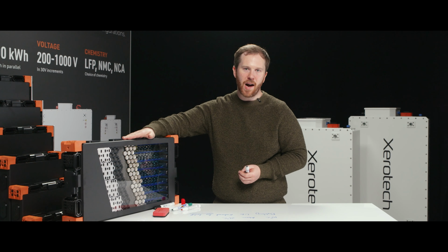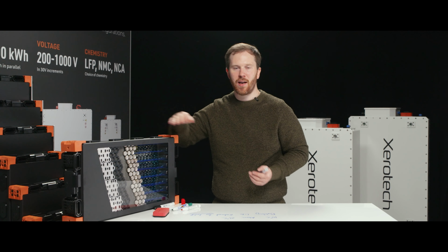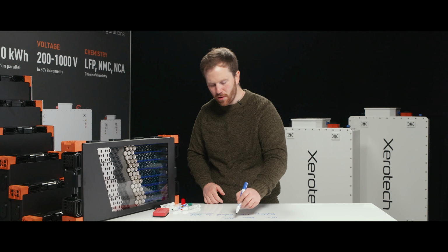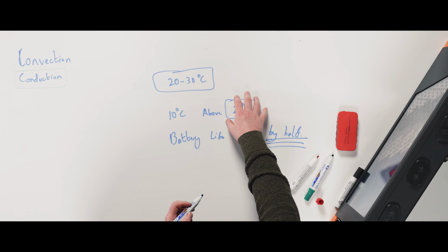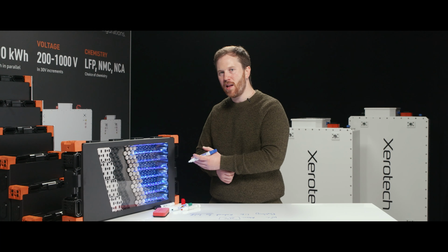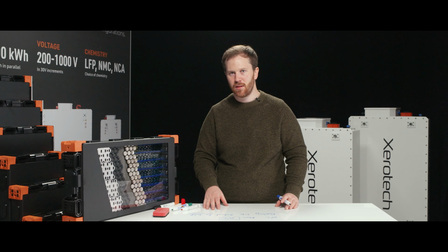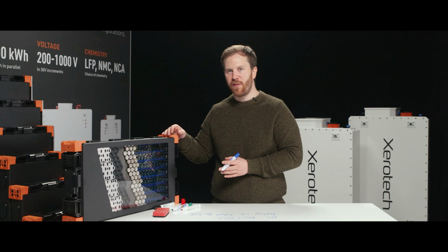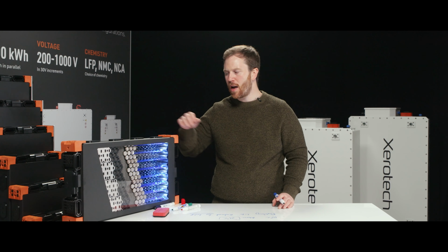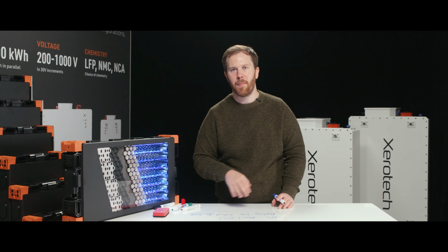Even in more mild applications, so these are batteries that have to operate for 8 hours a day or 10 hours or even 4 or 5 hours, it's really good to have thermal management, because if you can keep your battery at a nominal temperature, it's going to last a lot longer than a battery that has uncontrolled temperature. So thermal management is really important for day-to-day use cases to increase the lifetime of the battery and decrease the total cost of ownership. But also for high-performance battery systems, it's mandatory.